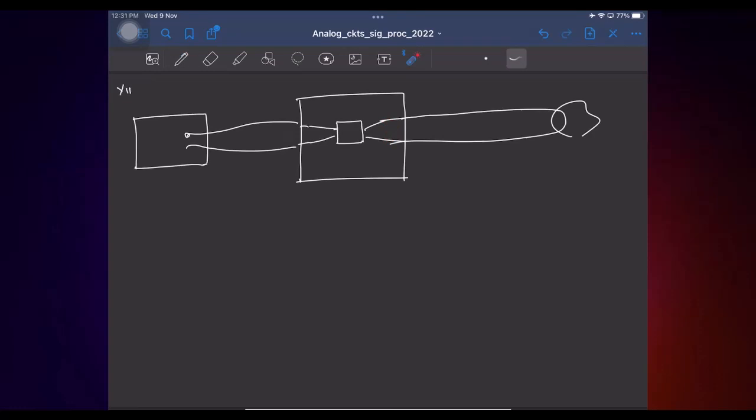We can use an op-amp and virtually short and pass that current through the resistance. But I need to measure it, right? How do I measure it? I need some equipment, isn't it? It will create voltage around that feedback resistance. But I have to short this guy, right? No. See, virtual short is different. What is virtual short? It says that 2 voltages are equal without actually shorting them. But here I actually have to short them.